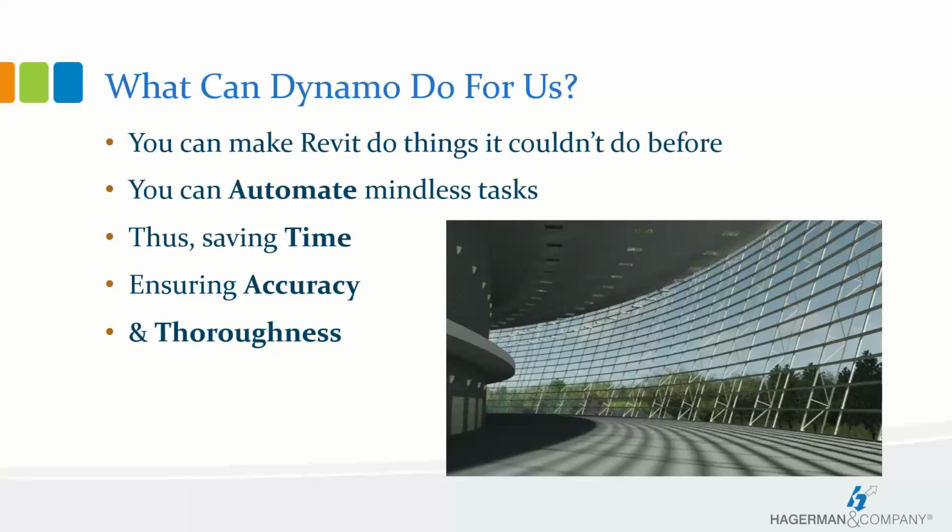And then the third benefit is thoroughness. If I needed to manually update a parameter on every column in my project, there's a good chance I could miss or overlook one. However, if I tell Dynamo to do this for me, I can ensure a far superior result.